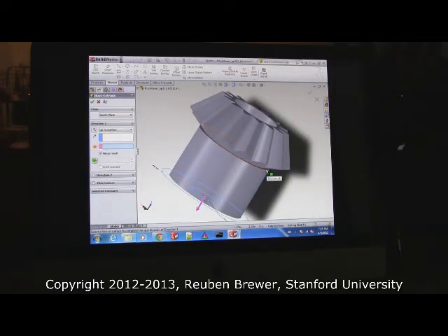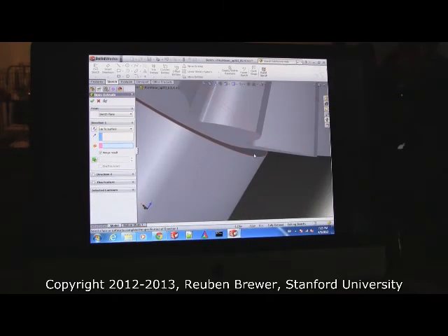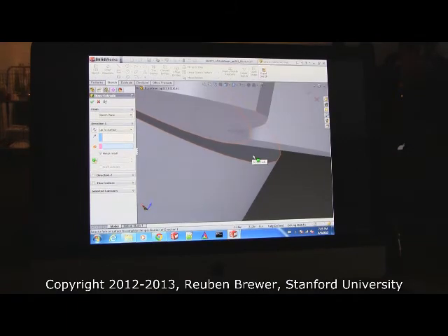So we're going to click, see this? Now this is very important. If you try to do something that is physically impossible in SolidWorks, it will crash. It's just the way it is. So in this case, you want to zoom way in, you see how it's highlighted red? I could get away with doing this, but I could also move my mouse at the last minute, select this or this, and there's a good probability it'll crash. Always zoom way in. Be certain. You can move your mouse quite a bit. You could spill your coffee and have a rabbit bite you on the foot, and you still won't move your mouse enough to click the wrong thing.